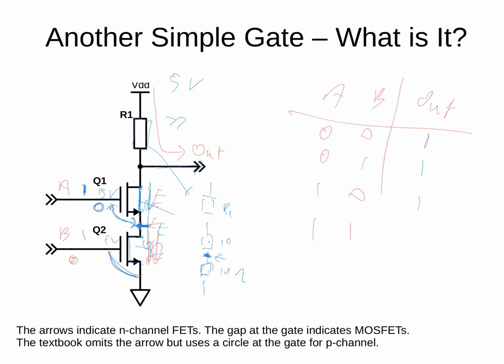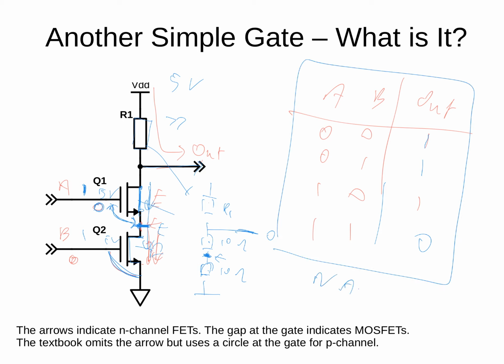Its channel resistance might also be, say, 10 ohms. And R1, we're going to assume, is much larger than 10 ohms. And so that means that most of the voltage drop is going to be across R1, or the output here is going to be close to the ground value. We're going to get a logic 0 coming out of this circuit. And so therefore, we get this truth table here, which we see to be a NAND gate. Remember, an AND gate would be 0001 for an AND, and we've got the complement of that. Therefore, this circuit here is how we can build a NAND gate.